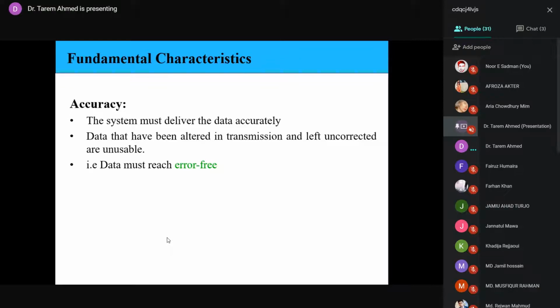Right? So in these cases, typically what a receiver will do is, he will try to maximize the probability of correct decision. He will say, okay, I will set a halfway mark, 2.5-volt. If I see anything below that, I will assume it's a 0. If I see anything above 2.5, I will assume it's a 5. And he thinks this is his best way of minimizing the probability of error. Right? But he cannot make it 0. And this is actually what is done.